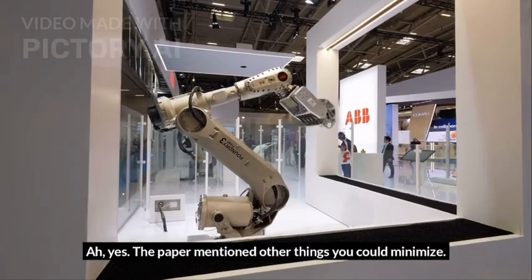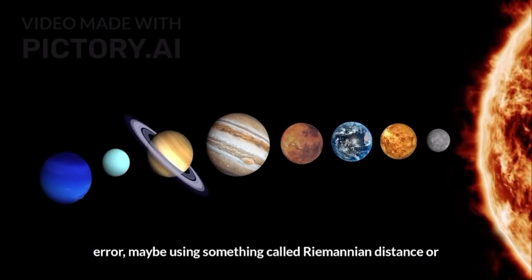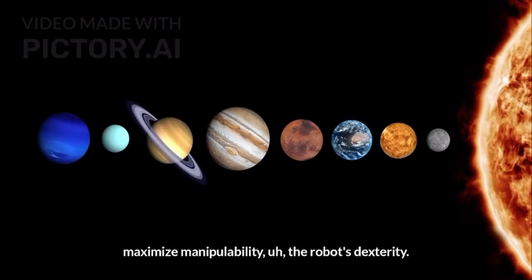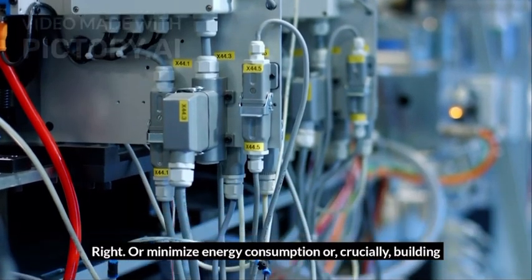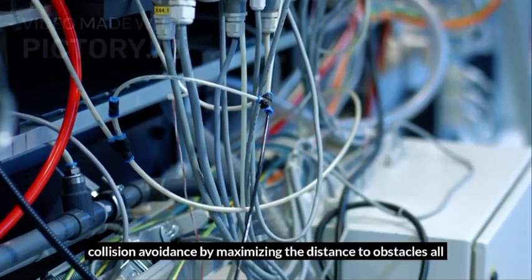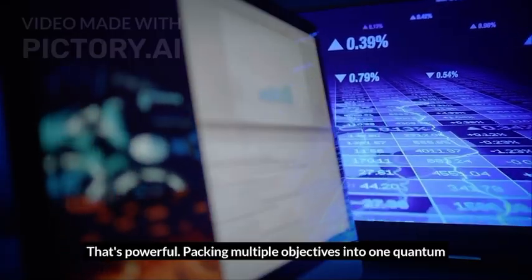Ah, yes. The paper mentioned other things you could minimize. Absolutely. You can build Hamiltonians to minimize orientation error, maybe using something called Riemannian distance, or maximize manipulability, the robot's dexterity. Make it more agile. Right. Or minimize energy consumption, or crucially, build in collision avoidance by maximizing the distance to obstacles, all within this quantum cost function. That's powerful, packing multiple objectives into one quantum search.